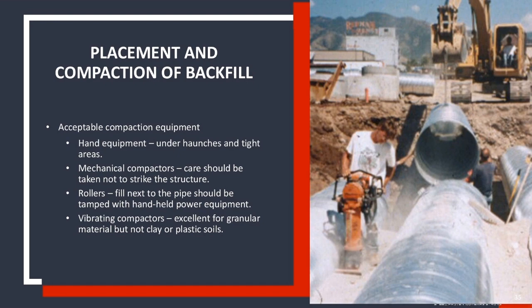Once you get up to about the spring line, you can start bringing in your mechanical compactors. You just want to make sure that you're not banging up against the structure and damaging it. Rollers can be used. I really like to see the rollers once we probably get up over the pipe. Like your walk behinds, I don't want to see any of the larger ones there, but walk behinds are fine. And then you've got vibrating compactors, which are really good for granular material, essentially settling out your stone, but you don't want to really use those on any type of clay or plastic soils.